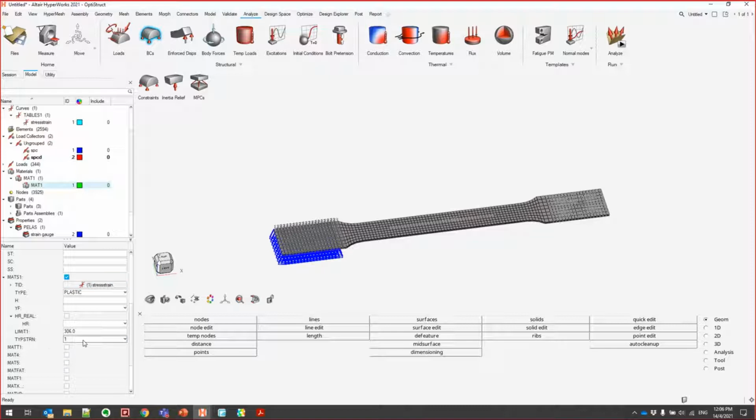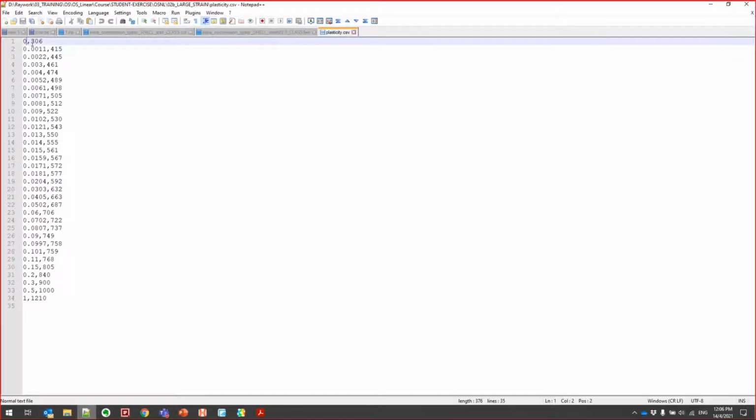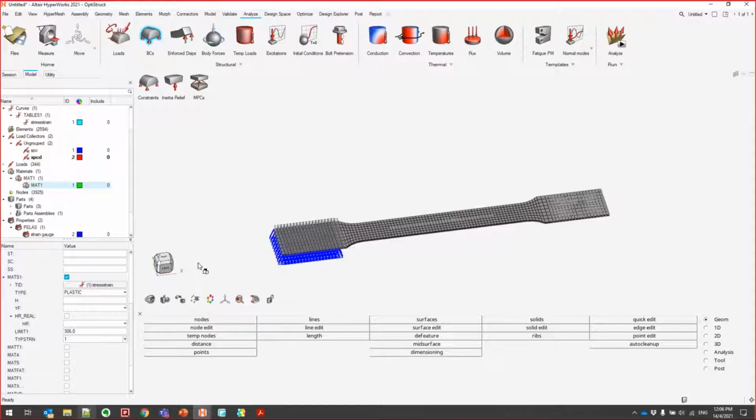It's not the total. What if you put it here as 0, or you didn't define this as 1? By default it is 0. But if you put in a stress strain curve where the first point is 0, and then 306, right? 0 and then 306. If you put it as 0, you will output an error.